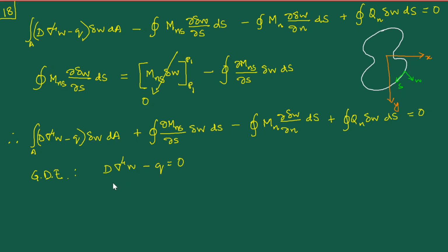But this classical plate theory has enabled us to reduce the whole problem to effectively a two-dimensional theory, even though we started out by considering a three-dimensional problem. By integrating out with respect to the z direction, we have reduced this to a two-dimensional problem, and this del 4, the biharmonic operator, takes into account all the derivatives with respect to x and y.